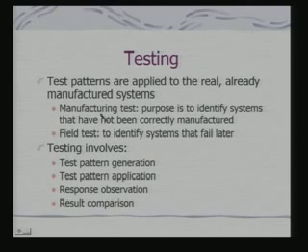It may be so that we may not apply, strictly speaking, manufacturing test to each and every appliance or each and every product that I am manufacturing. In fact, there are typical what are called statistical quality control standards and paradigms which are followed for the purpose of sampling out the products and testing them out.